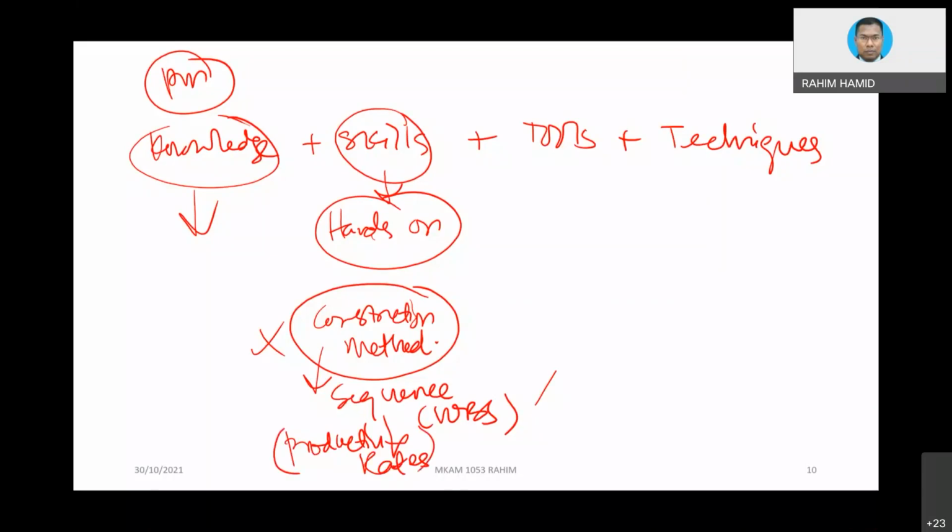Let's say you want to erect formwork, install rebar, do concreting, do piling, or do excavation with different machine tools, different manpower or teams. You need to estimate that. Why? Because productivity rate basically generates what we call the duration for each of the activities.